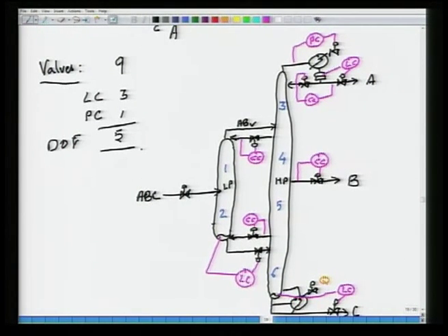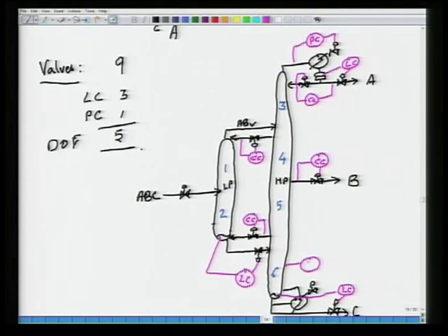And by composition control, you can also use temperature controllers. If the pressure is fluctuating, pressure compensated temperature set points. All right. So, when I am saying CC, it may be understood that it is being used interchangeably with temperature controller, with TC, with temperature control.